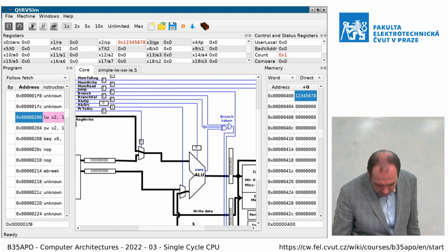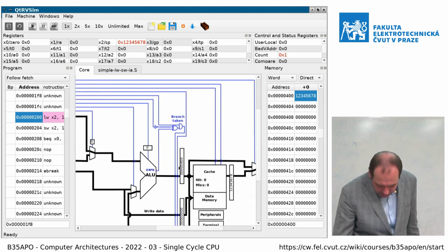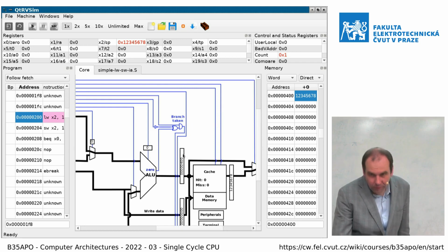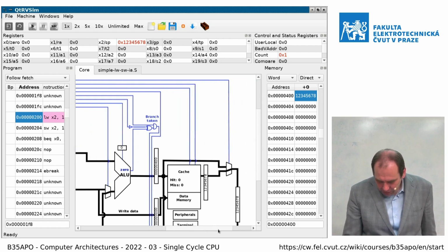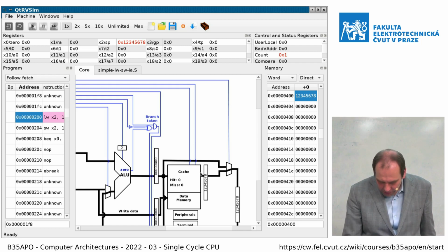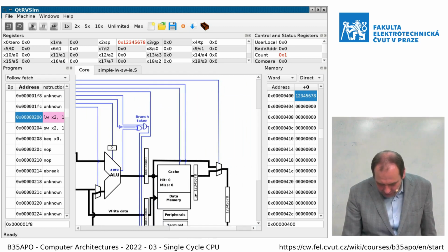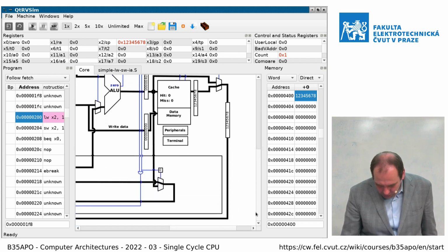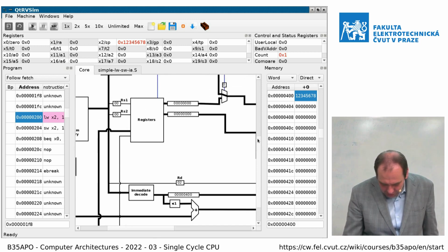And the value from the arithmetic logic unit is 400. And 400 is the address to the memory. So basically it goes to the right window here. And the memory has received a command, read data, memory read 1. So it provides the data here, and the data goes down and returns back to the write data port of the register file.